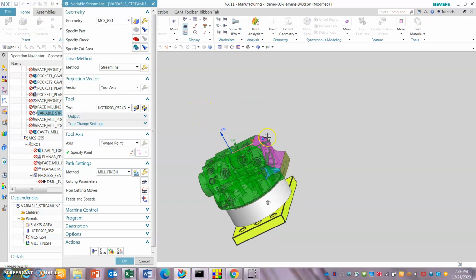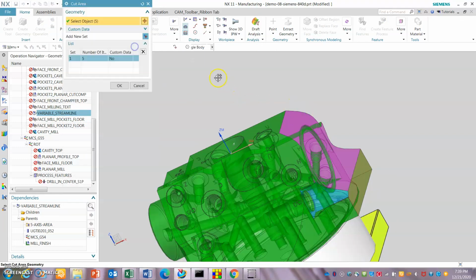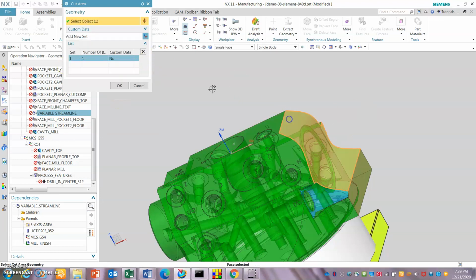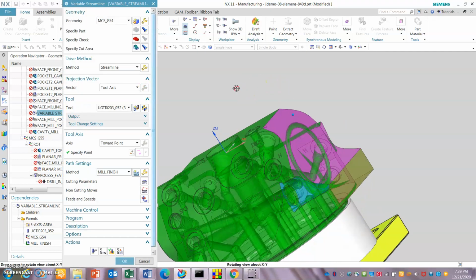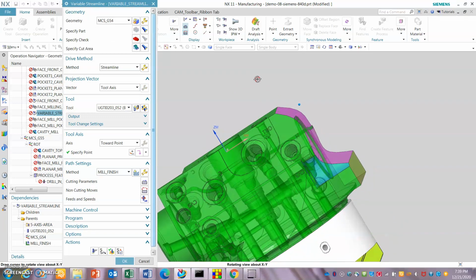Again, like I said, it's one of the templates I pulled up. You can see how we pulled the template and defined it. Right now we are doing an example for G43.4 or G43.5. G43.5 on a Fanuc is based on an IJK vector. Again, it's machine independent.